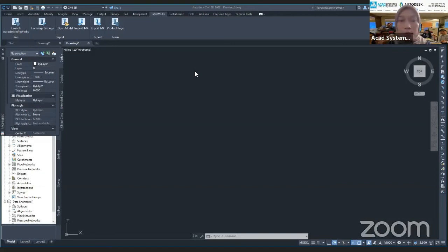This one will be backup master 10. You can always rename the civil IMX file that we're going to create. Make sure you remember that the IMX file will be in Autodesk Civil Data Files. Then I'm going to click Create.